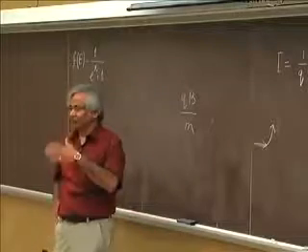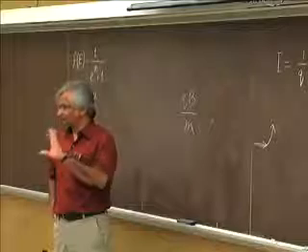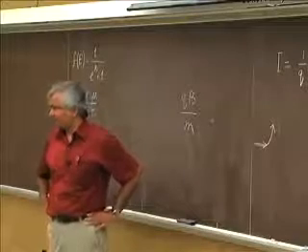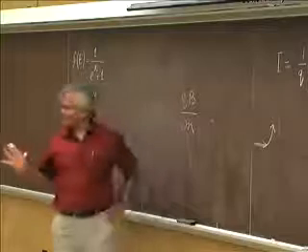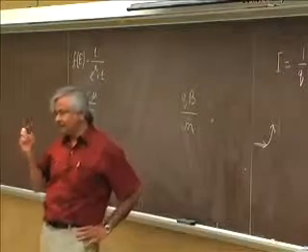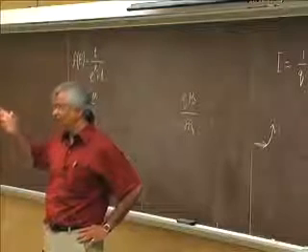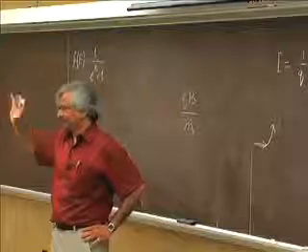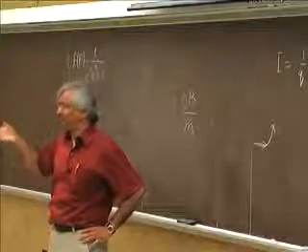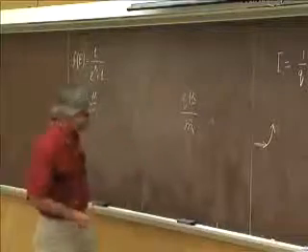And what I'm saying is that no, what really moves inside a solid is always a negative charge. What really moves is always minus Q. And the reason there is a difference is because the M is different. So an electron with a negative M you could conceptually convert and think of as a hole with a positive M. But you shouldn't do both. I mean, don't make it a hole with a negative M. Right? That's the point.